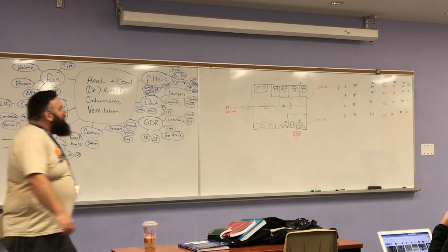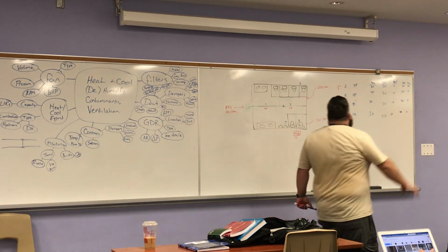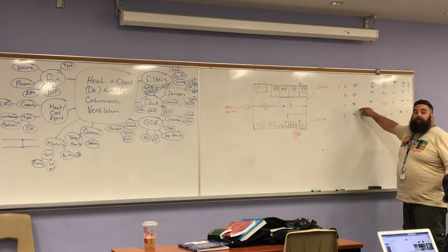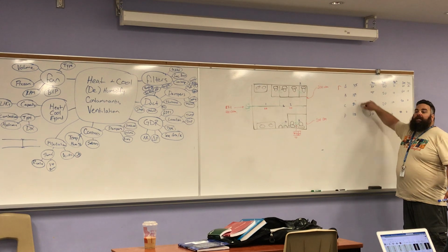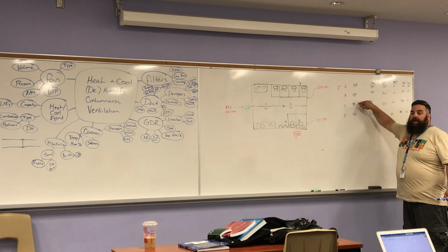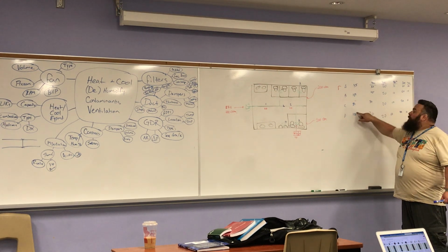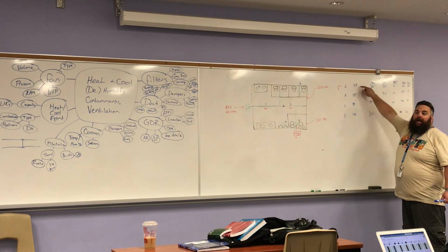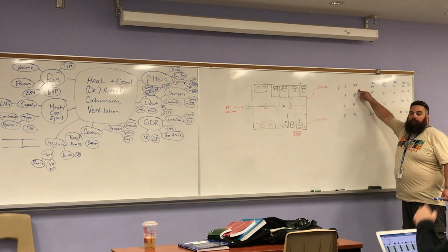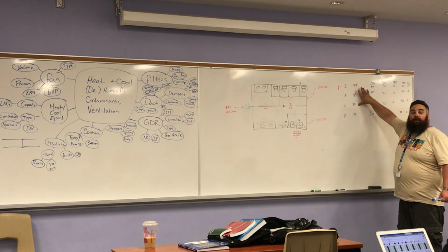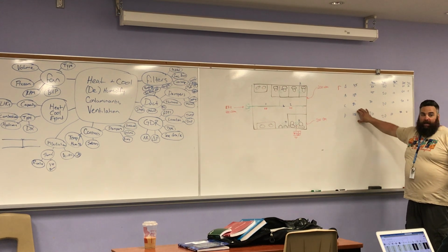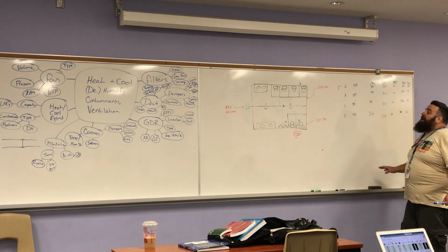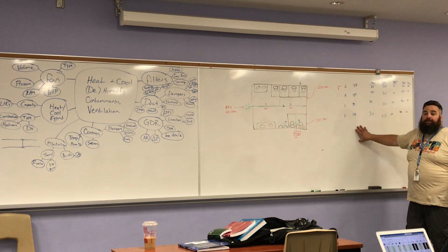So because these ducts are shorter, I can make those smaller compared to this because I want those pressure drops to be the same. Okay? I want a little bit more friction here and a little less friction here. Because I want the air to see them all equally. If I made them all the same size, what would happen?